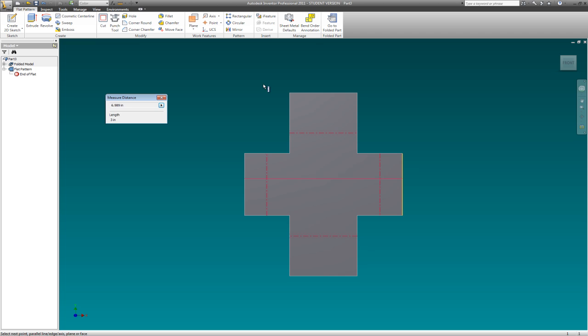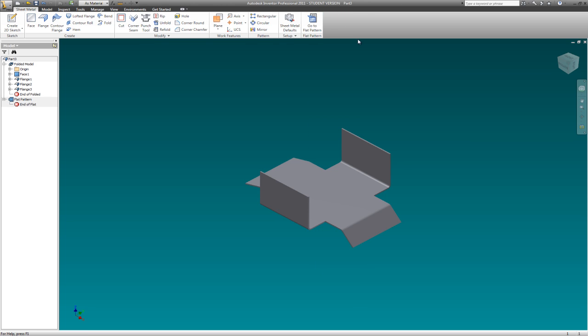And this one here, what was that one again? This one was, this should be a total of 5 plus 2 plus 2, which should be 9, and you can see how much shorter it is. So it's just really, that's one of the things that you're paying the money for in Inventor, is to do this mechanical factoring in for the K factor.